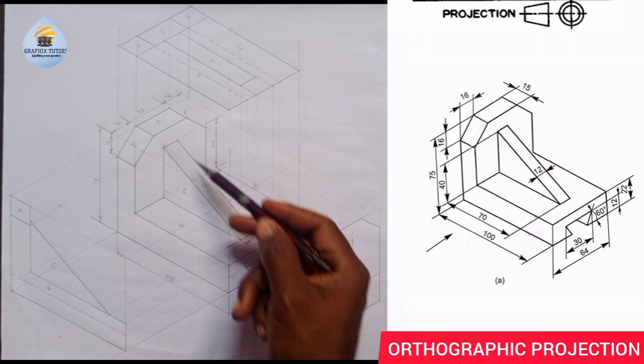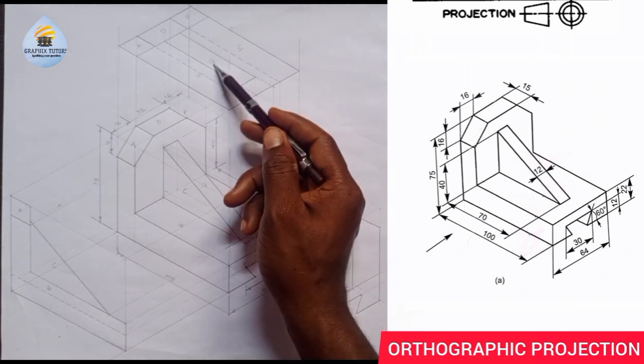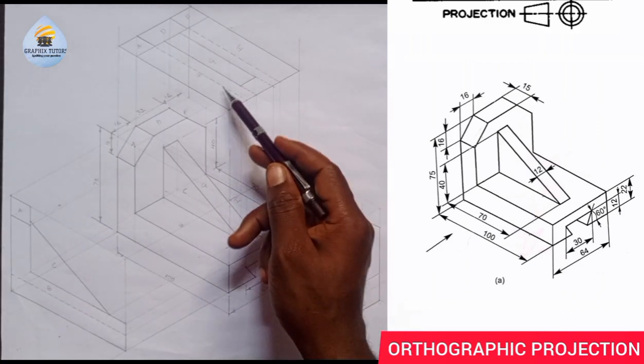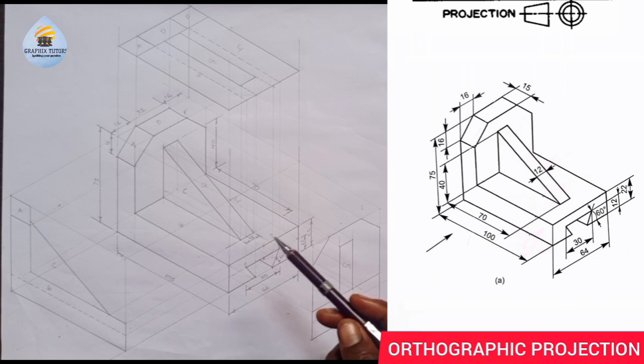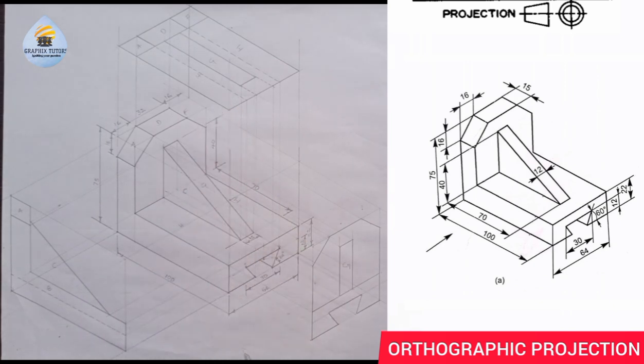And we have this shape here, which is this. You see it as a straight line when you're looking at an inclined line from a distance. You see it as what? A straight line. So this is G. This is also G2. So what do you notice? When you see the same figure G from the end elevation and the plan, you should know that it is inclined. So when you see a shape in two different elevations, you know that shape is inclined. So this is inclined. I'm seeing it here and here, right?